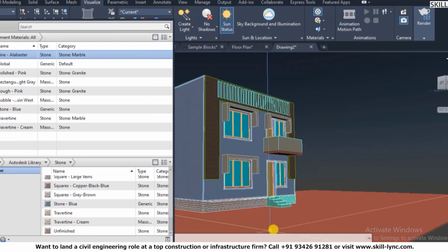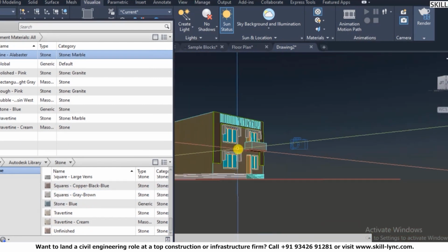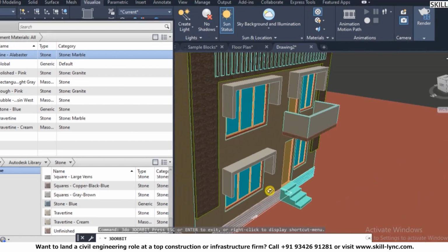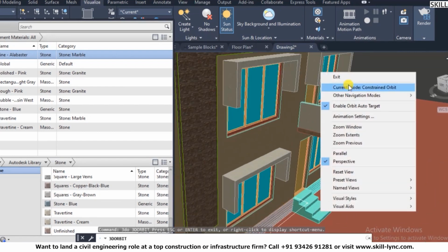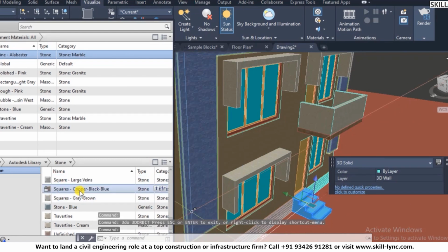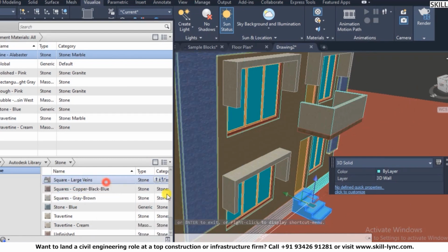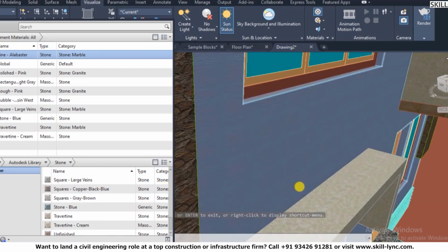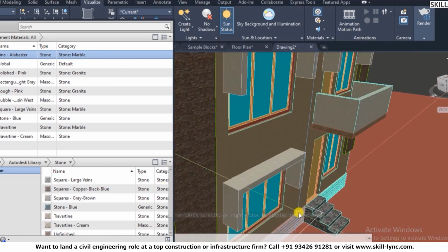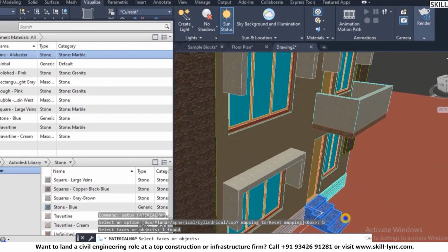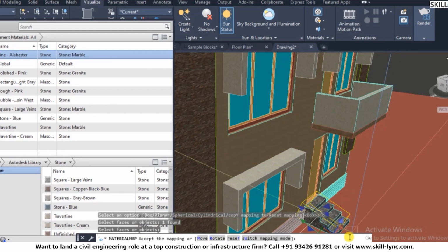It doesn't mean that it can practically go, but you can play with the colors and the material and see how it looks. So you can always assign to selection. Go for the set UV and check the box mapping if it fits over here, and press enter.